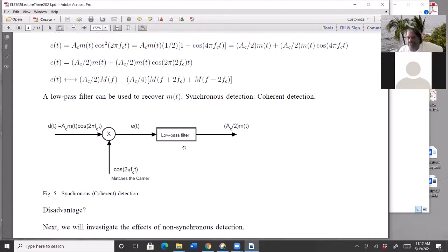Or at 20 kilohertz is okay, because most AM radio stations don't worry about high fidelity. So they think their signal ends at 15 kilohertz. They don't really worry about anything higher than 15 kilohertz. So maybe they will put a filter at 17 kilohertz cutoff. That will only give you this. Alright guys? Okay.